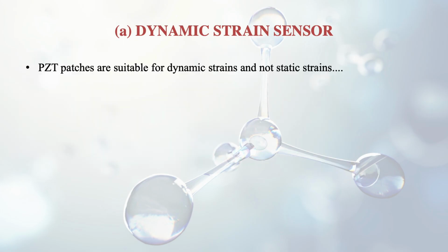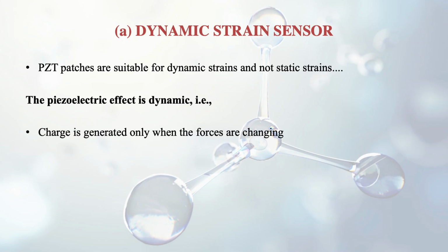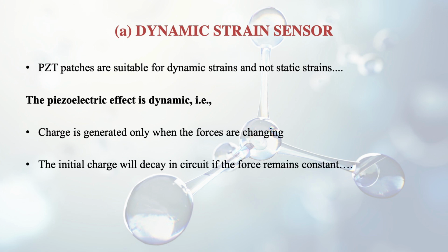It should be noted that the PZT patches are suitable for dynamic strains and not suitable for static strains. The reason is that the piezoelectric effect is dynamic in nature, that is, the charges are generated when the forces or the stresses are changing. If we have only a static force, the initial charge will decay in the circuit and the potential difference will go down to 0. So they are not suitable for static stresses.